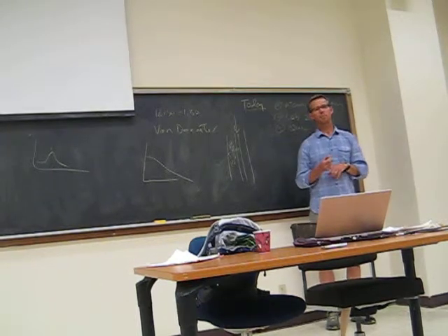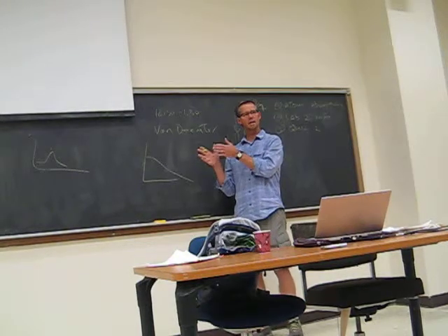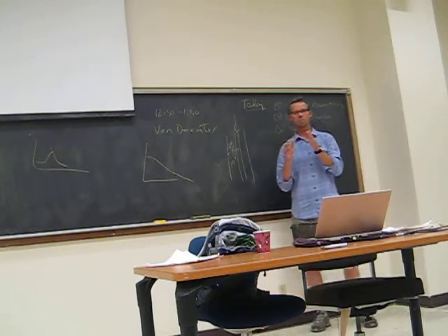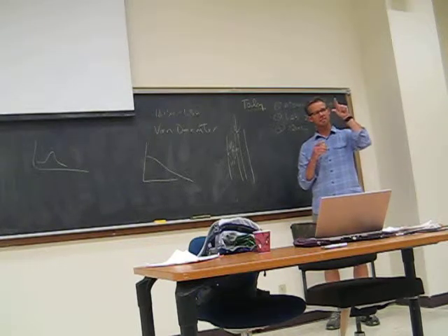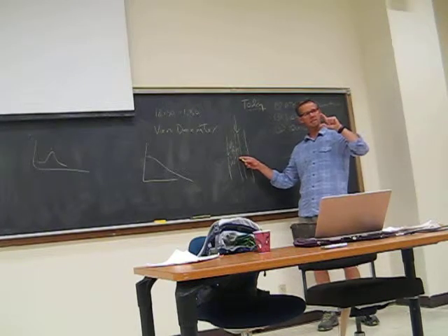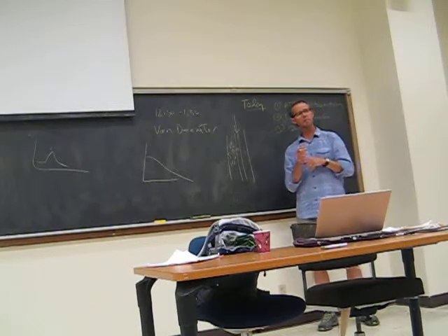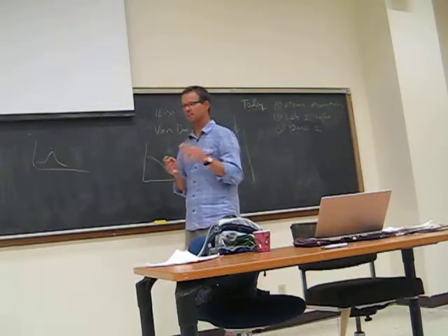And we've always known that generating a Van Deemter plot with an ion chromatography system fitted with a suppressor is always challenging, because the suppressor is greatly influencing this process as the flow rate changes, right? And so it's a bit of a confounder, but we've had success in the past, but not guaranteed success.